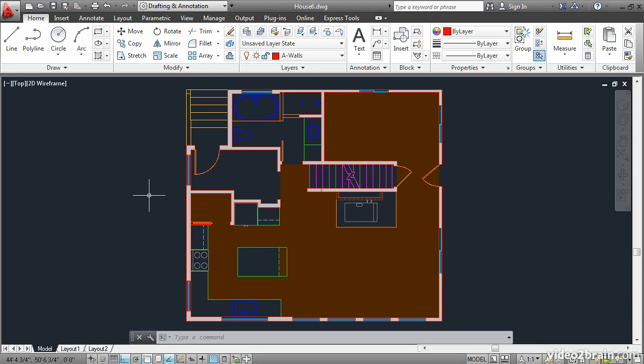By default, all the lines you draw in AutoCAD are just 1 pixel thick. This looks good on screen because it gives you clean, crisp lines, and this helps you to draw accurately. However, it's a different story on paper. For centuries, traditional draftspeople have known that physical drawings look their best with at least 3 different line weights. In this lesson, you will assign different line weights to layers, and will visualize this temporarily on screen.